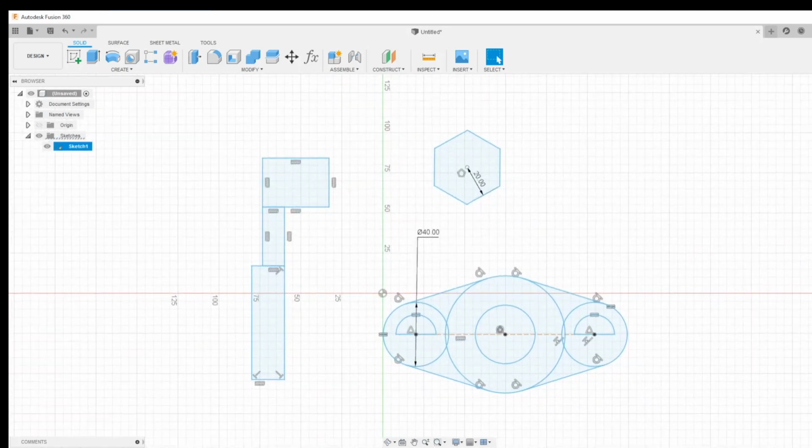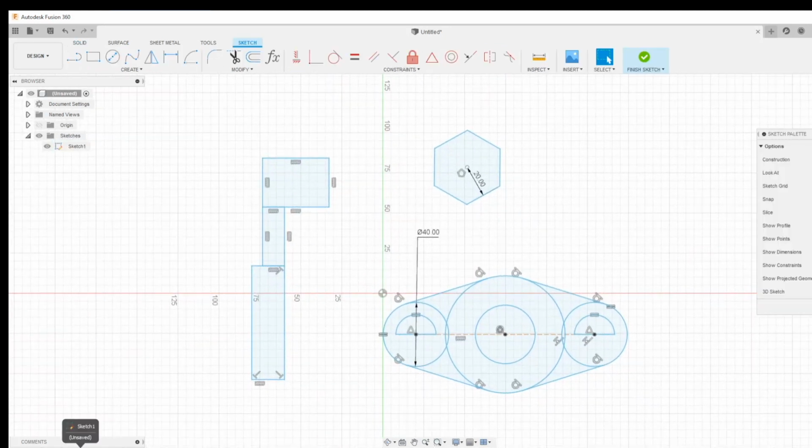For example, I can roll back up to the sketch definition and change the dimensions of the shapes I've drawn at the beginning. I do so by using the Sketch Dimension tool. When the field is available for change, you can prompt the parameter name and set it. Notice that it is suggested in the drop-down list as I'm typing.